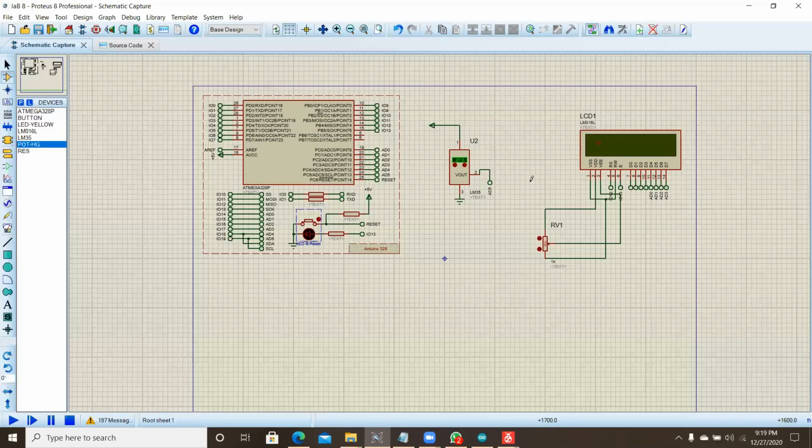In this lab, we worked on the ADC converters, which convert an analog input voltage to a digital value using successive approximation. The minimum value represents ground, and the maximum value represents the voltage on the AREF pin, in 1 LSB.